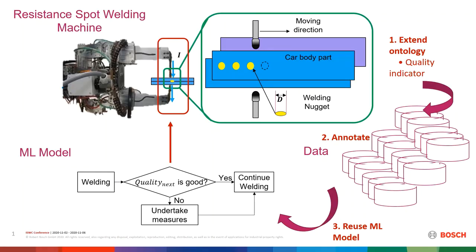Potentially, many observed parameters of the operation and wearing characteristics of the equipment can serve as quality indicators. For example, the spatter during the operation can signify poor quality. And of course, various methods based on sensor fusion are constantly developed. Bosch has a special Q-value that relies on statistic features from sensor data. It's a calculated parameter, often present in the datasets.